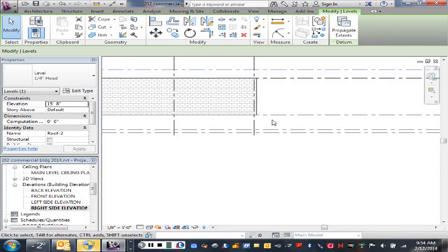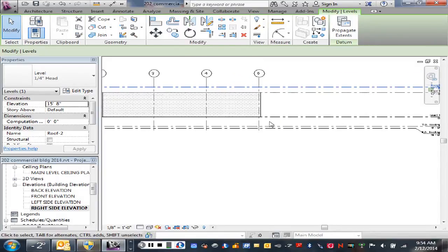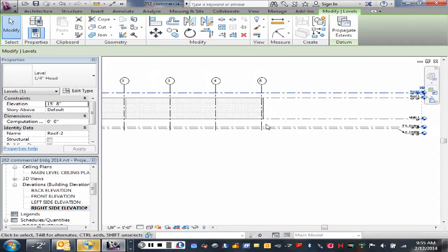So we're going to say that our precast concrete planks are going to be 8 inches in depth and thickness. With an 8-inch precast plank, we can span up to about 30 feet roughly. But again, we can look that up and find that information out. Precast concrete planks, you're going to be required to have a topping of concrete over top of that because the planks are irregular on top.